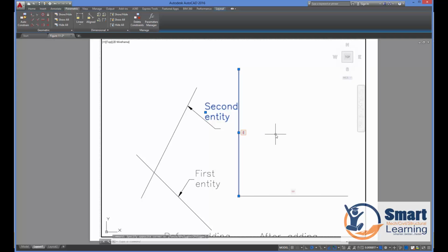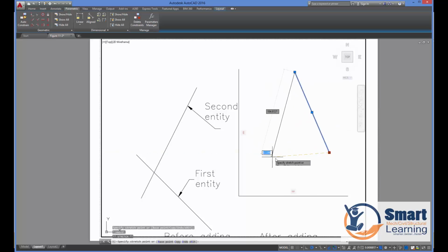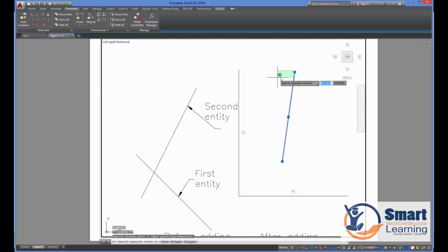And by default, if you don't apply this, let us say we go for a line and create one line, what happens is, if you hold the middle grip, you can move it, and if you hold any end, you can in fact rotate and reshape and resize that. And this is the power of this constraint and the parametric tab, you can see, which is introduced, and all these geometric constraints you can assign to fix the location or orientation or type of object you are looking at.